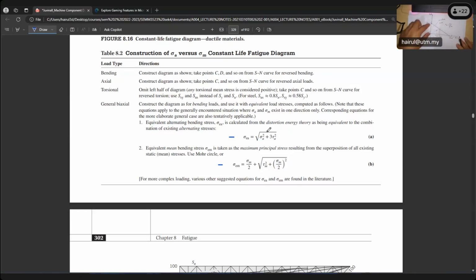And also if you're using the y-axis, sigma e alternate, this is your border. So this will be your strength alternate. Strength alternate over sigma ea also gives the safety factor. Based on this line, basically the mathematical representation of that is here. Understand that, class? This is the mathematical. You can use directly the formula.